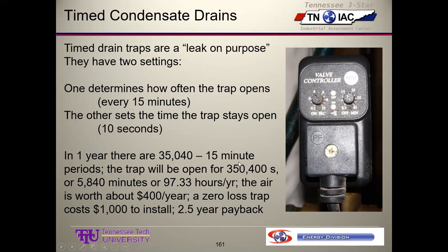Okay, here's a little example. So you can see a close-up. So this guy is set for when it opens, it's going to stay open 10 seconds, which is the maximum for this one. And it's going to open every, which one? I guess I read it. You have to be a little careful what direction the 0 point is. I think it's pointing towards the 15. So it looked to me like this thing was set to open every 15 minutes and blow for 10 seconds.